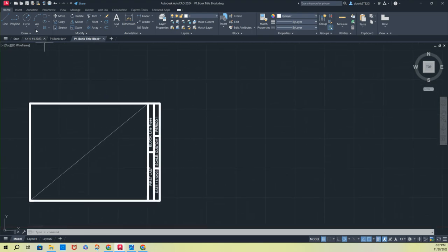I'm going to draw my box over here with just a line. Click here and start moving to the right. When I see that green dotted horizontal line indicator, I'm going to type in the number 8, hit the enter button, go vertically, get a vertical green dot indicator telling me I'm at 90 degrees, type in 5.5, enter.